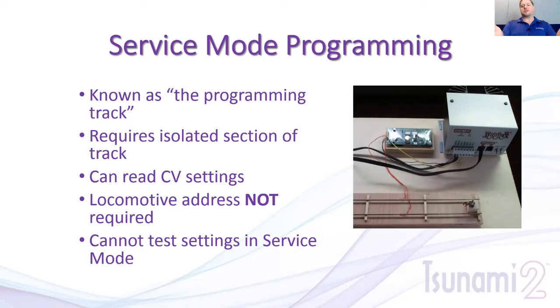Your decoder should sit there, be quiet, and just communicate yes and no with the command station. If you're getting noise on the programming track, you either have a power leak getting to the programming track or something else is wrong, contact our service department.